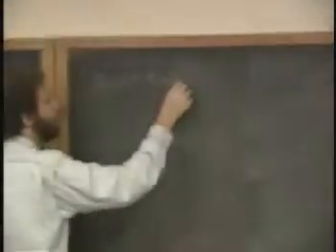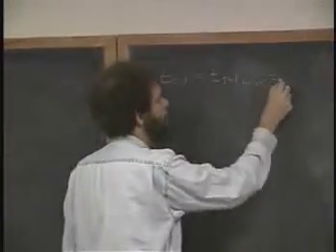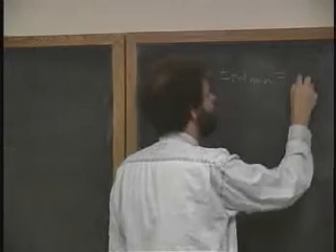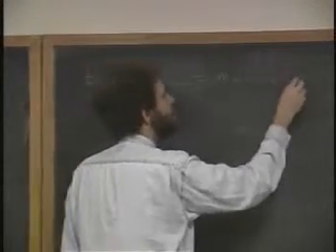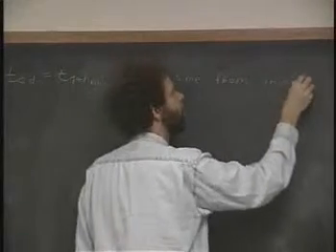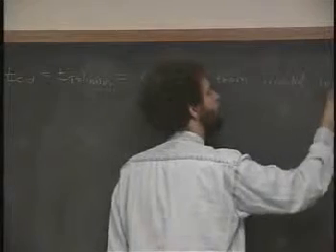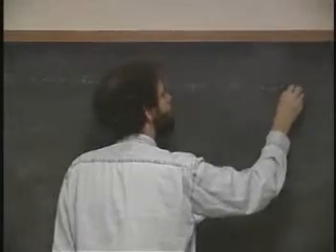So the contamination delay T sub CD, which is equal to TPD min in most uses throughout the world, is equal to the minimum time from invalid input to invalid output.